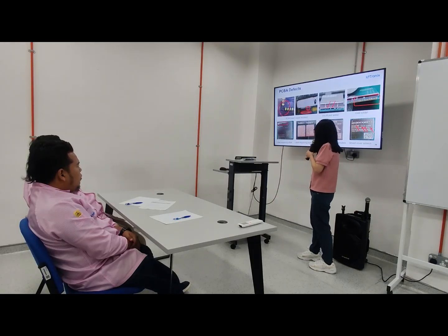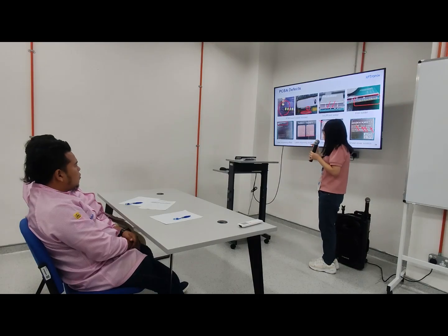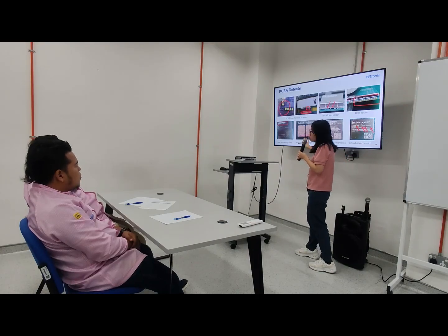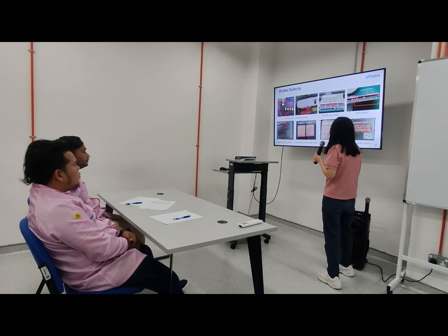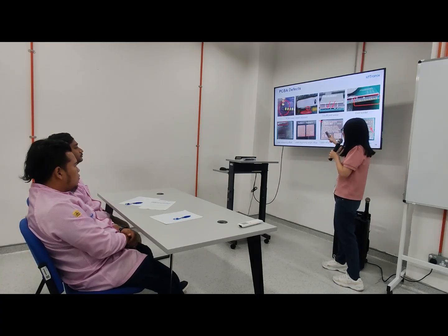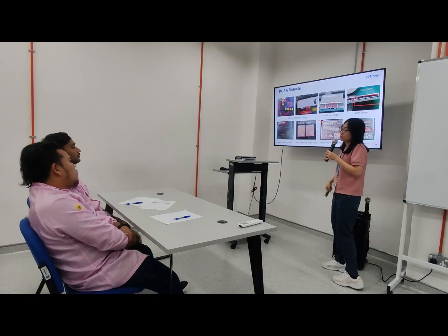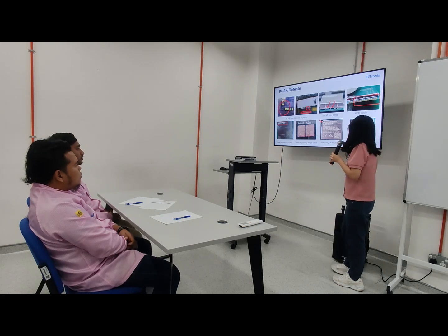Then this one is laser engraving angle offset. It's supposed to be flat, but this one is slightly lifted. Angle lifted, that one also cannot. Make sure all the content is at the middle. Don't let it shift to the left, right, up or bottom. Okay, this one, incomplete means the G wording. It's also slightly shifted upwards, so the G wording becomes incomplete.